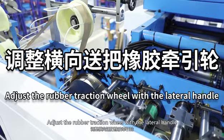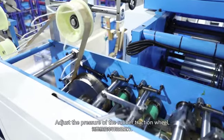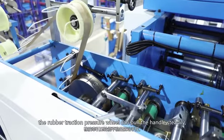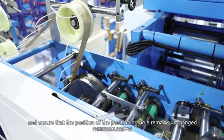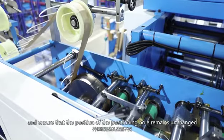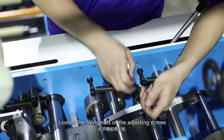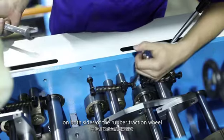Adjust the rubber traction wheel with the lateral handle. Adjust the pressure of the rubber traction wheel. The rubber traction pressure wheel can pull the handle steadily and ensure that the position of the positioning hole remains unchanged. Loosen the fixing knot of the adjusting screws on both sides of the rubber traction wheel.